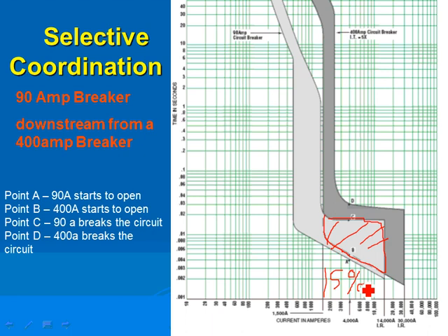Now, if you're using fuses, it will give you a better coordination. You can see if you look at some fuses, they're sharper in their cut, so they give you a better coordination, depending on what type of fuses you use. But they have a drawback too: single phasing situations, and they're not adjustable, they're replaceable. But this is an acceptable level of coordination. To get a full coordination, guys, you almost always have to go to an adjustable circuit breaker. Fully adjustable.